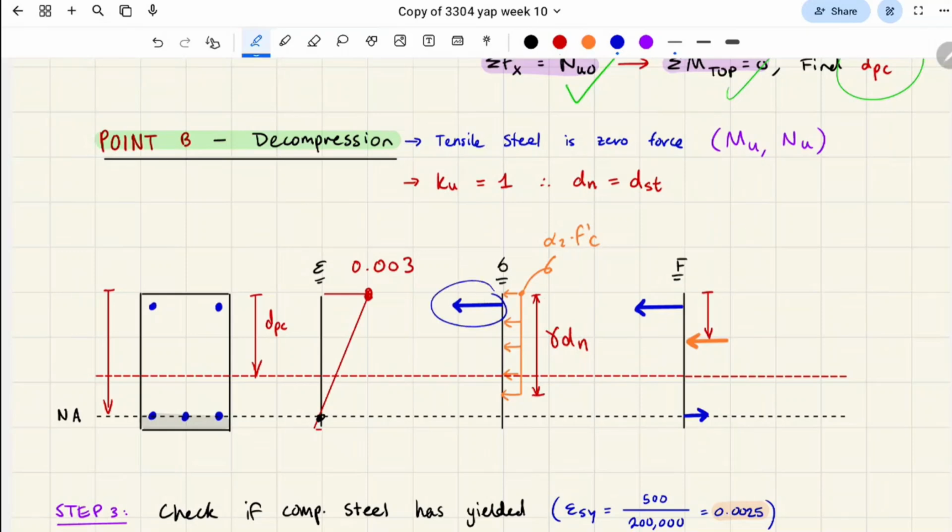Arjuna, what type of bars are these on the top side? Are they tensile or compressive? Well, I think the top half is above the neutral axis, so it's still in tension. No, there's another one: compression. Remember, 0.003 is always on the compressive side. This number is the ultimate compressive strain, so these are the compressive bars.